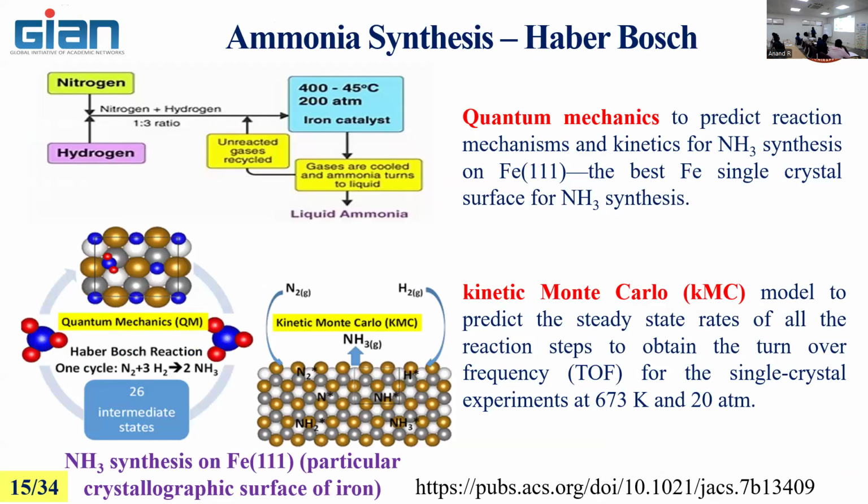So in the ammonia Haber-Bosch system, nitrogen reacts. Why are we not using the same 1:1 ratio for both? If you use the 1:1 ratio, then the reverse reaction is possible. Suppose we use 1 mole of nitrogen and 1 mole of hydrogen, then ammonia formation happens, and the ammonia will be immediately dissociated into nitrogen. The reverse reaction is not going to be controlled. Whereas if you increase the hydrogen to 3 times the nitrogen, then it will be very difficult for the reverse reaction, because our ultimate aim is to produce ammonia, not to dissociate ammonia into nitrogen again.